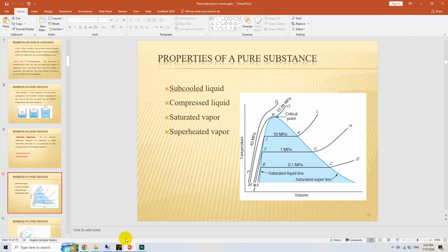of the water. Water converts from liquid to vapor. This occurs completely in BC. If we put more and more heat into the water, the liquid water converts completely to vapor at point C. After that, if we put more heat into the system, volume and temperature increase. That is what we are familiar with as superheated.